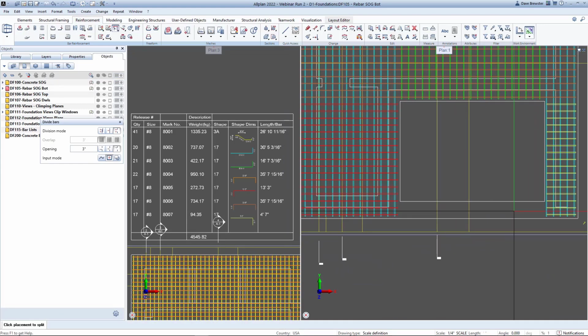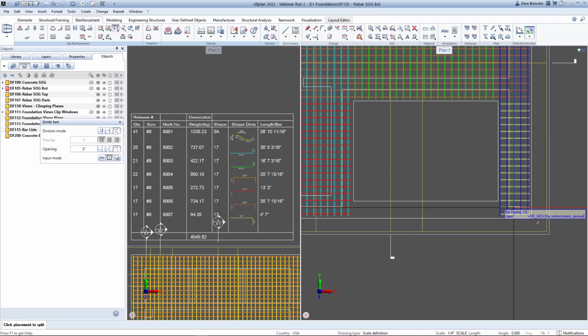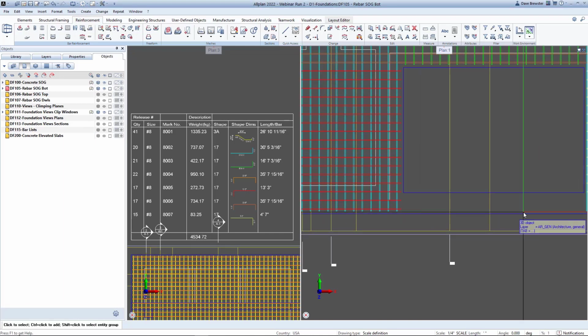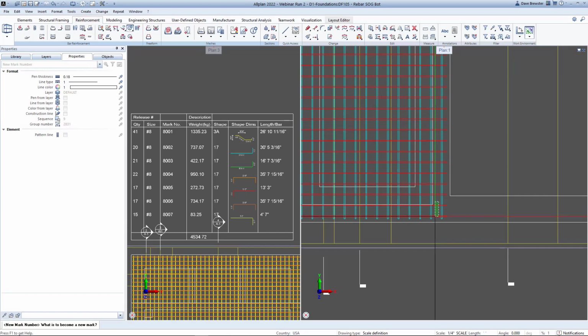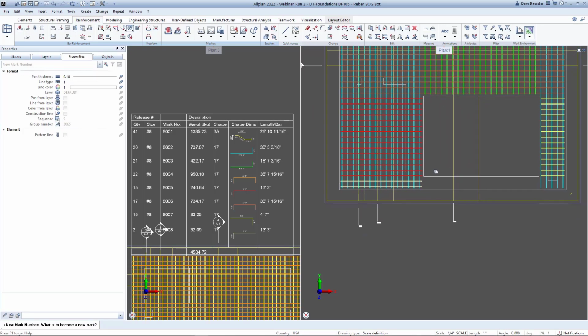Next tool that I'm working on here is our split bars command. Very unique tool across the industry. I've now just split a bar on an opening, and the bars have created, again, 2 separate ranges. In this range, I can go in and pick bars that I want and don't want part of this range, because there is an actual beam designation that goes in here later.